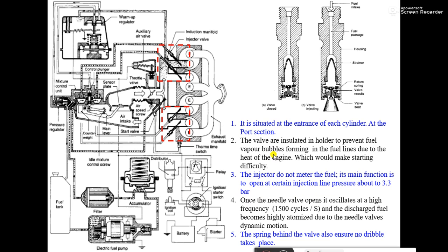So जो भी ये जो injection K-Jetronic system हम देख रहे हैं, तो K-Jetronic injection system का aim ही है कि continuous injection करना है. Continuous मतलब क्या? Once engine is started till the end, इंजन हम जब तक चाबी off नहीं करते इंजन का, till that point we are making a continuous injection. मतलब एक बार नल खोल दिया फ्यूल का, that is injector ने एक बार नल खोल दिया, ऐसे फ्यूल आने को start हो गया, फिर गाड़ी जब तक हम off नहीं करते तब तक fuel injection will continue.